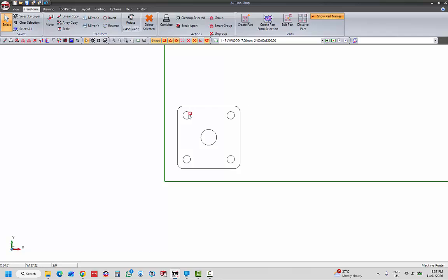Allow me to demonstrate. Remember that we just used the break-apart function on the flange, so it is really just 6 individual shapes at this stage. You can tell because all shapes are blue when selected, meaning they're all external shapes at this point in time. For the exercise, I want to manually make several copies of the flange.